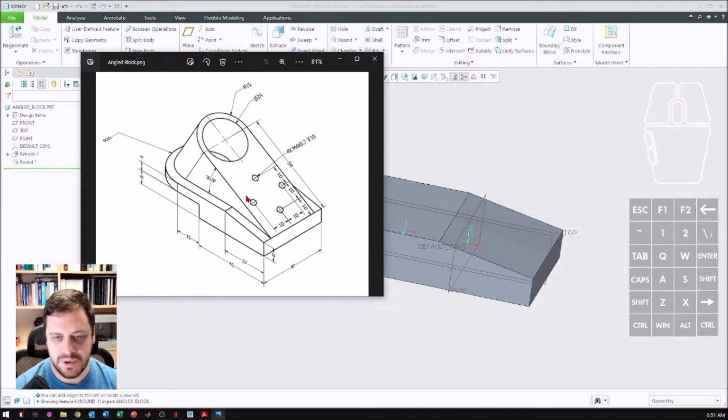So the next step that we want to do is the actual plane itself. So what you need to do is create a datum plane that is 30 degrees from this flat section through here. And that's quite important because when we sketch off that plane, you want everything to meet up flush with these two particular surfaces. If you tried to extrude that outwards and use some side sketching and the like, you'd probably maybe get away with it, but it's going to be very, very clunky.